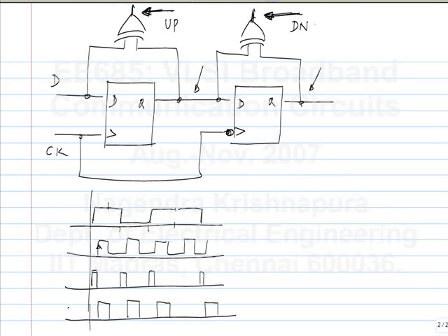Because the long-term jitter in the data can be quite a lot, because of the jitter in the transmit source and so on. Now if you clock it with a perfectly periodic signal, you may end up with a problem. Let's say you know the average frequency of the data, so you somehow magically get an exactly periodic signal with that average frequency. You clock it, now the data is jittering back and forth. So you are clocking it at different points of the bit period. And the total data jitter could even be more than one bit period in the long term. So you are sampling the wrong bit. Whereas the clock and data recovery circuit should do better than that, in that it should track the jitter in the data and go wherever the data is moving and retime it.